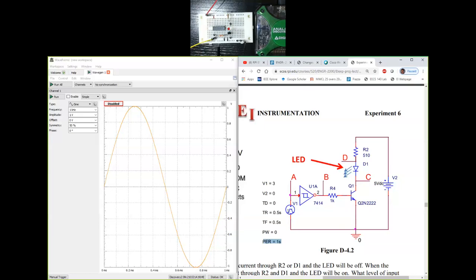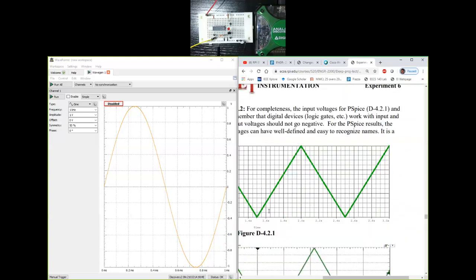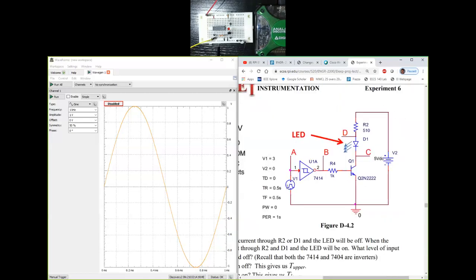So if you're generating a pulse, but the rise time is half a second and fall time is half a second, and that's your total time of 1 second pulse wave, then it is essentially a triangle wave, which should look like this, right? So half a second it rises, half a second it falls, and the total pulse width is 1 second. So it's essentially a triangle wave that we are trying to generate in this particular WaveGen.